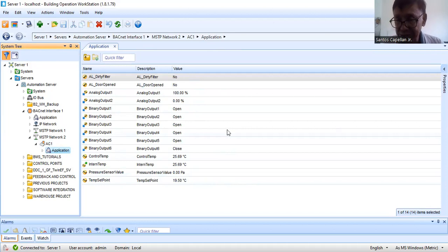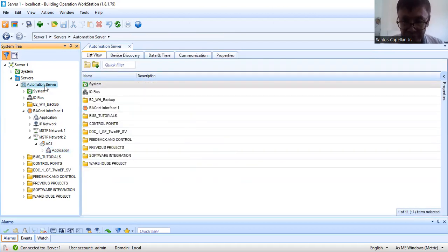Okay. So, guys, this is how you are going to do the initial software integration of a thermostat to your system. Okay, so let me repeat it. First step, do the field connection for your thermostat. Just make sure the power and the communication will not be reversed. If you reverse it, then you have a big problem. You will fry all of your thermostats.